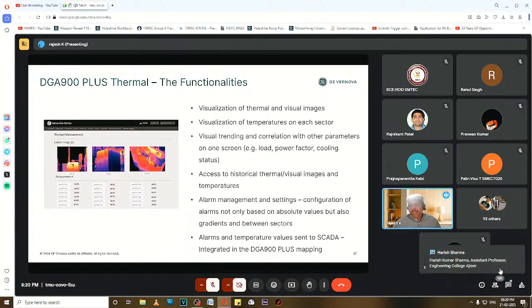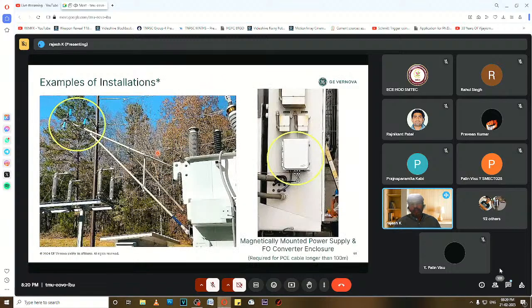This specific area is having an alarm, and you can also see over a period of time. In summer with the same load, last year with the camera we can identify the temperature was X and today it is Y. So you can also see a variation from year on year, not necessarily from yesterday to today, but year on year for the same load. We can always correlate and we can generate a report. So it will give a full fleet of information for the transformers.